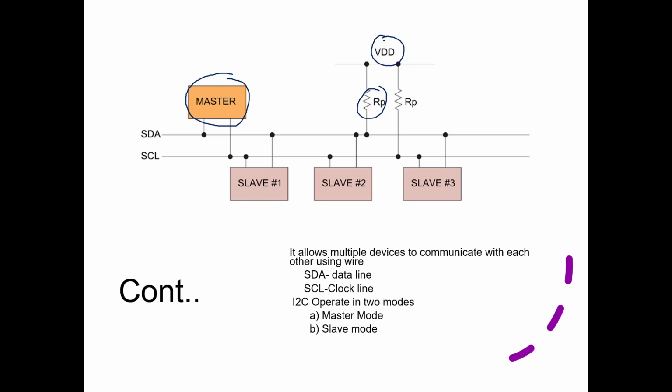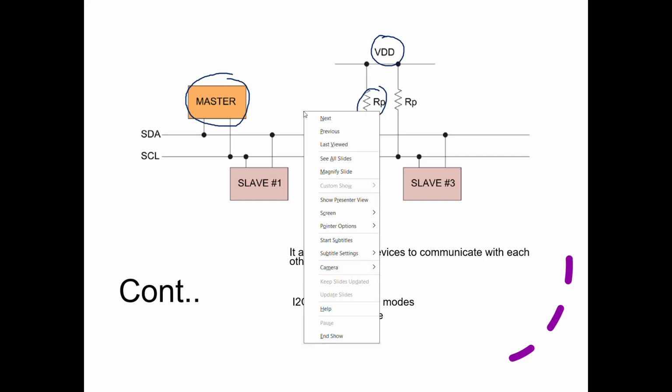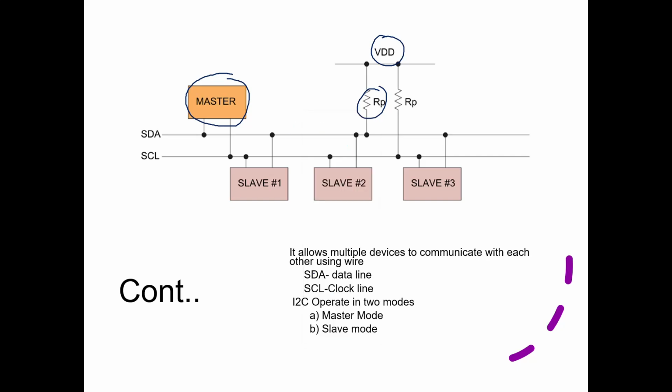So that is the beauty of this I2C protocol. Only two lines, a simple protocol, which can build complex designs. Peripheral ICs to processors and controllers also communicate with it. It is an intra-board, short-distance communication within devices, and it communicates effectively. It always allows multiple devices to communicate with each other using the SDA line. SDA means data line. SCL means clock line.